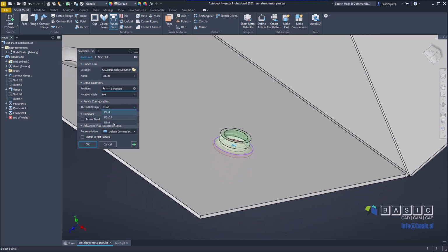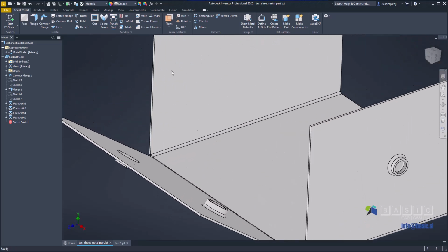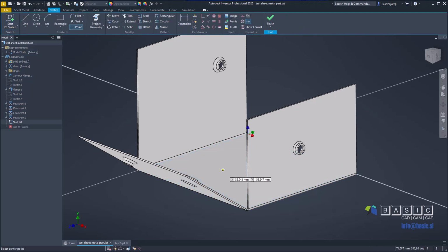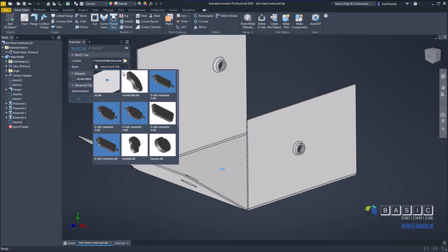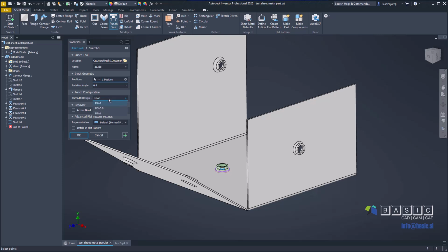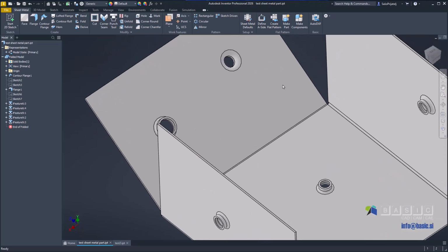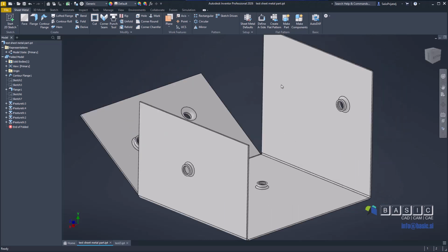I will say it's M8, and you can see it's a bit bigger. Let's create another one. I will create a sketch, let's say here, and create a point, and click another one, and this one will be maybe a bit smaller, size M5. So like this. In this video you learned how you can create a punch tool with threads that can be used on sheet metal parts.